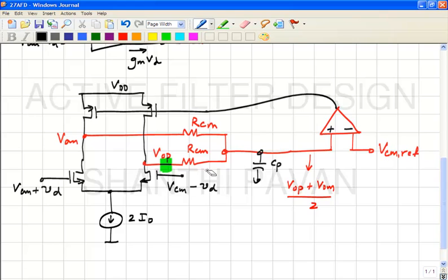What do you think you can do? I mean, why is there a problem in the differential part? The problem with having resistors was that in the differential part, current flows in this fashion, correct? And thereby this current will steal some of the current that the transconductor is putting out.